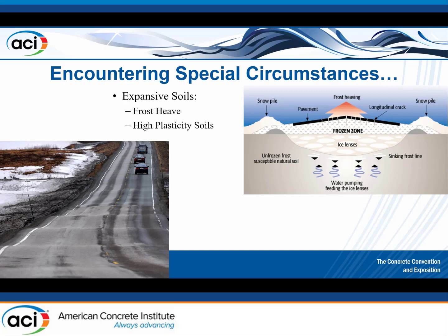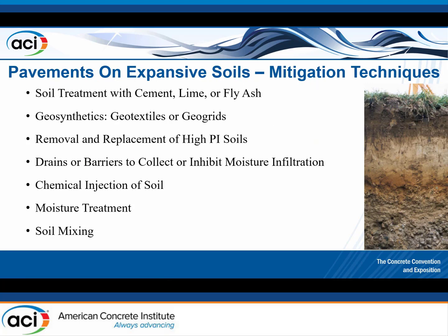Now, when we encounter special circumstances, those being areas in which we have frost penetration and heave, and also swelling of our soils, we need to do some things a little bit differently. We just don't leave the soil in the condition that it's in because we can get issues like this. Now, this is a flexible pavement, but those are typically frozen areas that cause that type of expansion. Believe me, when I was in consulting, I dealt with a lot of litigation on expansive soils. They do a lot of damage to roadways, and everybody starts wanting to point the finger when pavements fail before they're supposed to. So litigation is a concern when we talk about expansive soils.